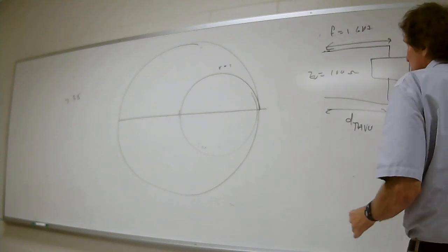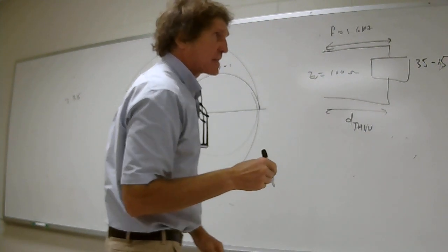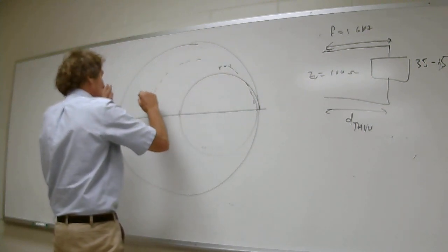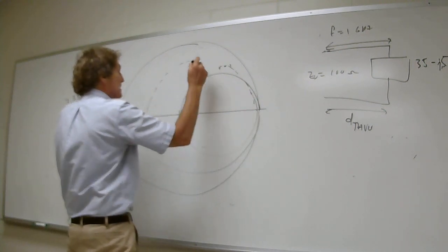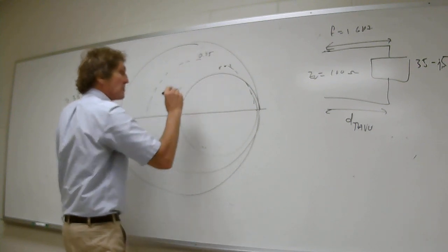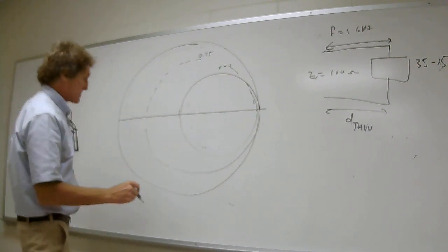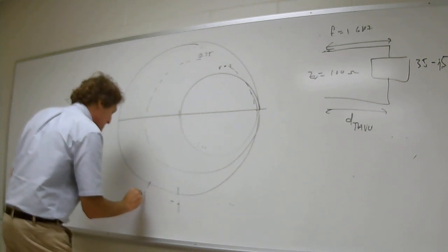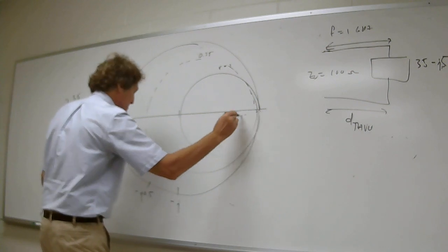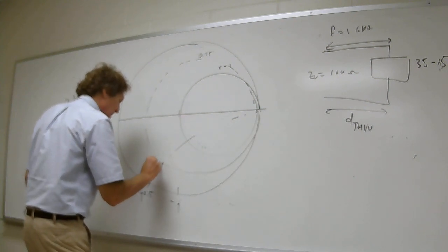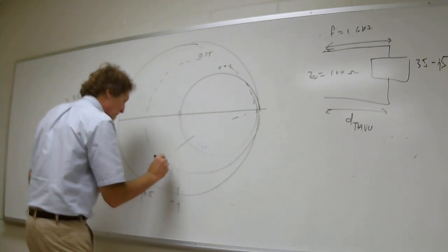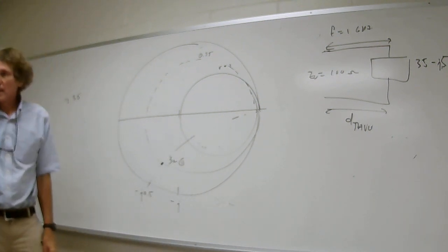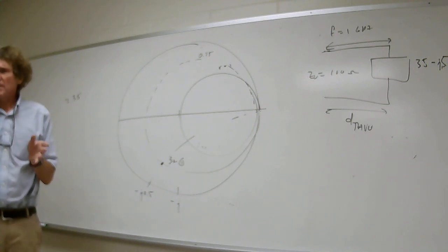If you've got a Smith chart and you look for that, 0.35 is a circle, about here. 0.35 is the real part, and minus j0.5 is down here. Now this is minus j1, so minus j0.5 is about here, and the trajectory will come here. It should be about here, your zL. Y'all follow me, class? We did this one, didn't we? Yeah, we've done this one.